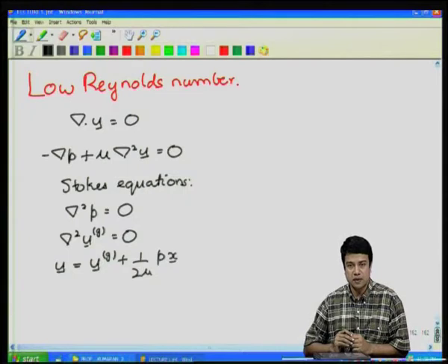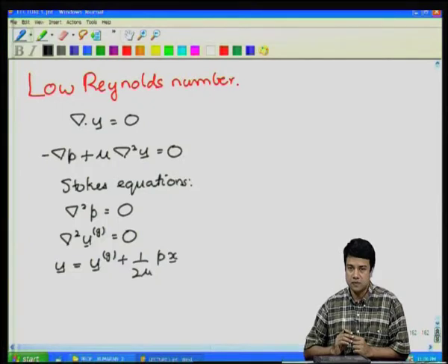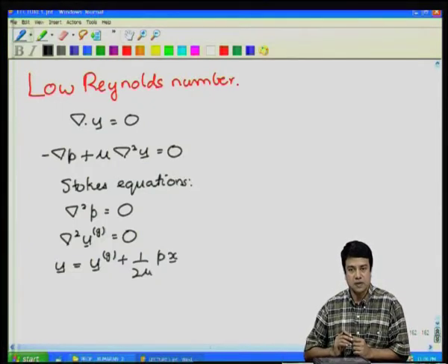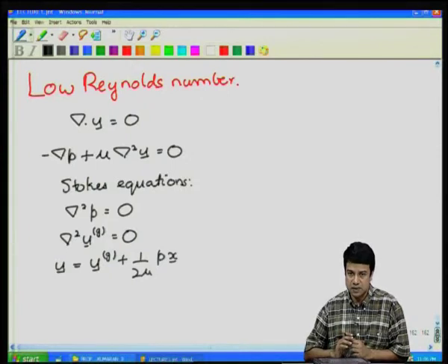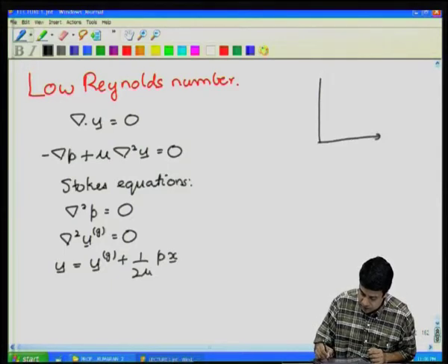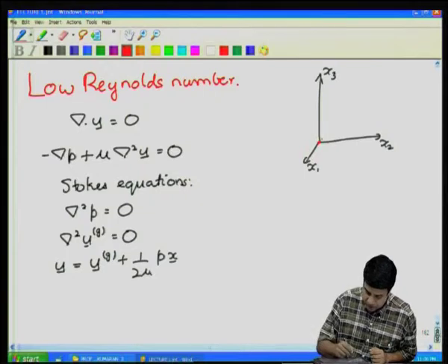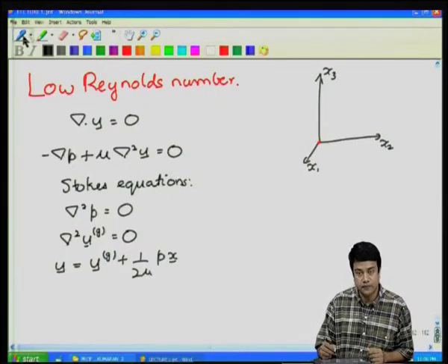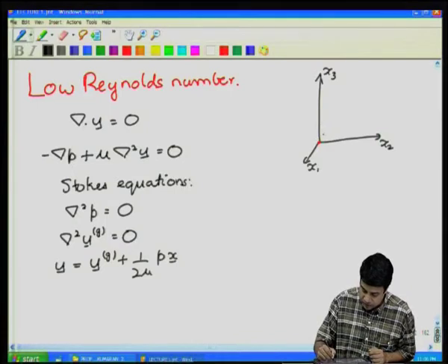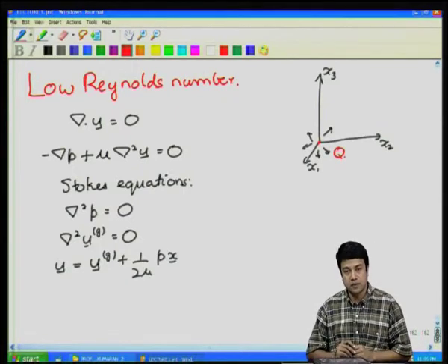It started off with the fundamental solution for a point source. We have done that earlier. Del square T is equal to 0, a point source at the origin. The temperature is equal to Q by 4 pi k times the radius, where r is the distance from the origin. So, if I have a coordinate system with a point source at the origin, this is an axisymmetric coordinate system. You know that if that point source, the total amount of heat coming out per unit time is Q.